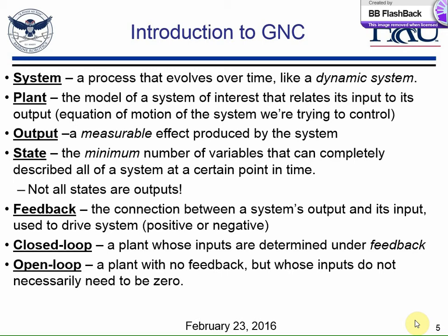So surge is bow, sway is starboard, and then your yaw rate is how you spin from X to Y, right? Because we have a Z-axis positive down system. So that's something in a marine vehicle. It'll be a surface vehicle. Underwater vehicle, you'll actually have 6 kinematic states and 6 dynamic states, right? Because at that point, you have to operate in full 6 degree of freedom space.